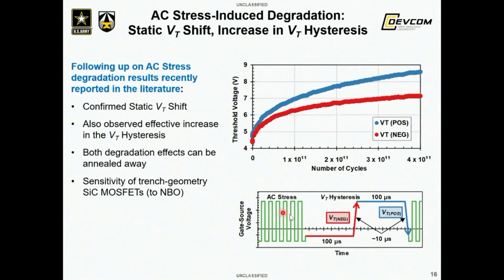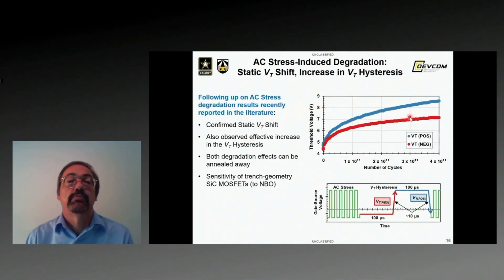And here I'm just showing a schematic. So we apply the AC stress, and then we do the hysteresis measurement, and then we return to the AC stress to produce these curves.